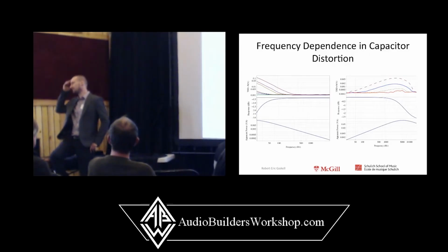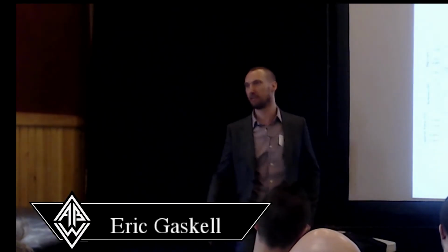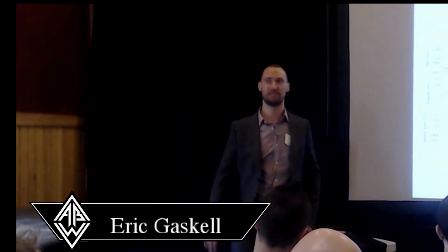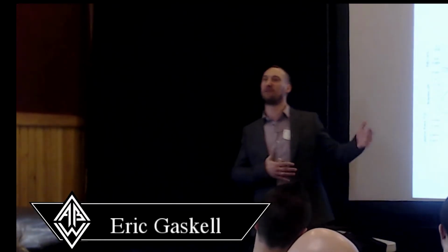How about silver mica capacitors? You see those used a lot instead of ceramics. Well, yeah, silver micas are the best. They're amazing, but they're just not available in large sizes anymore. Sure, they're great though. Unfortunately, they're too expensive to produce. Also, you don't see polystyrene anymore. Not in large sizes. Those are really nice just for feedback loops and op-amps and that sort of thing.